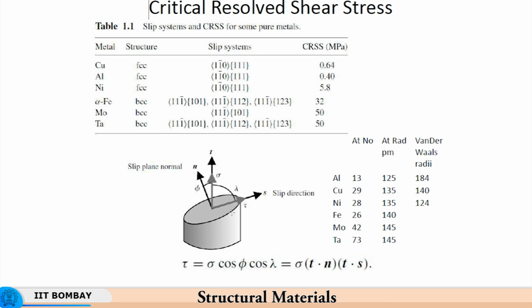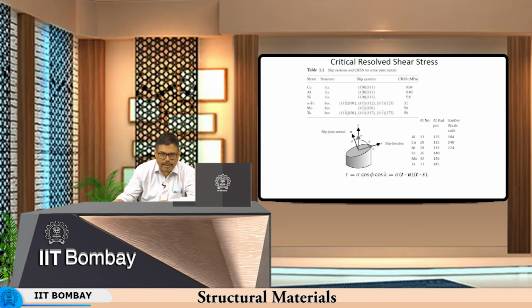And so now S is the slip direction, because the arbitrarily oriented plane which we have considered does contain this slip direction, whereas N, the normal, is perpendicular to this particular plane. So basically this angle phi with respect to the tensile direction is also the angle between the slip direction and the horizontal, right.